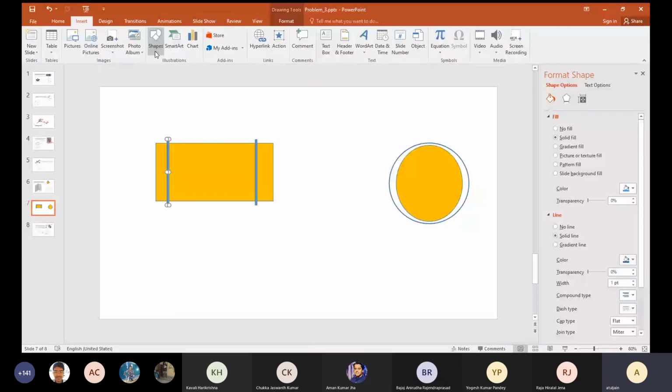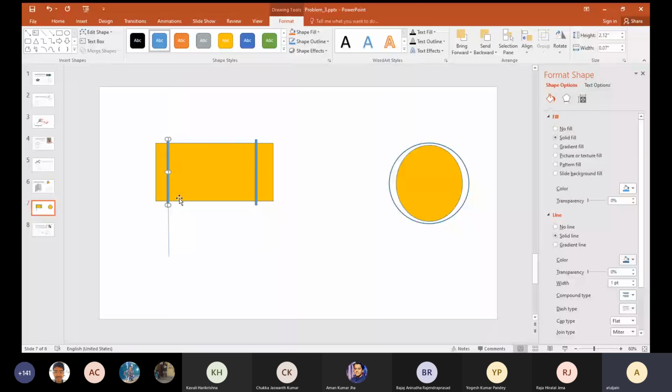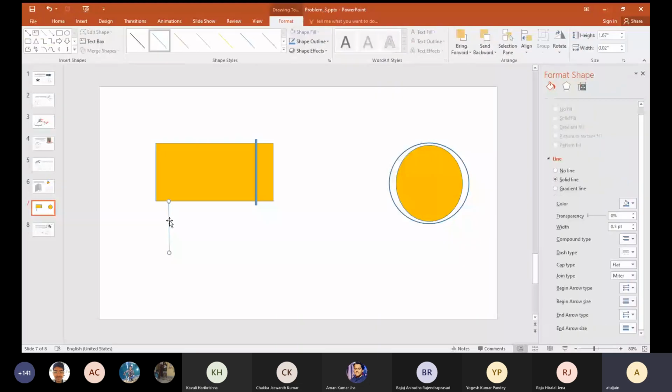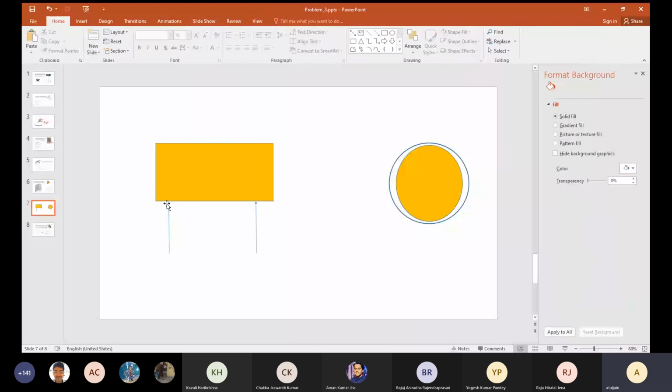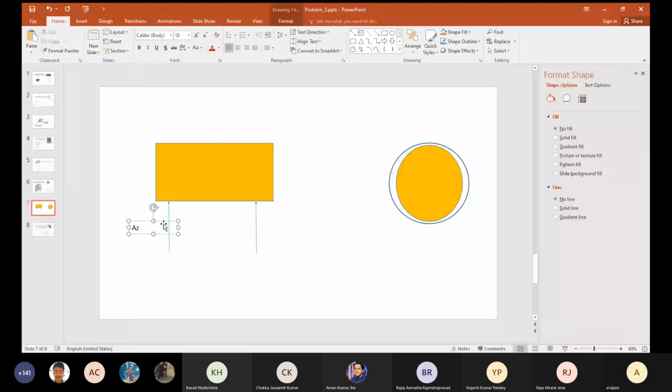Let us draw the free body diagram. So my point is, when I'm drawing the free body diagram, I will only look at one ring. One ring is allowing rotation, but not allowing movement in this direction. So I put one reaction. Similarly, the other one is also putting one. Let this be AZ. Let this be BZ. Now, AZ and BZ need not be equal.